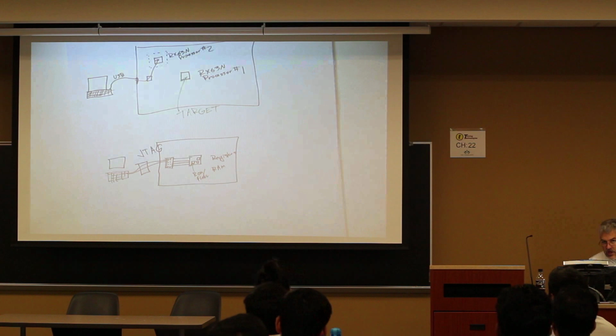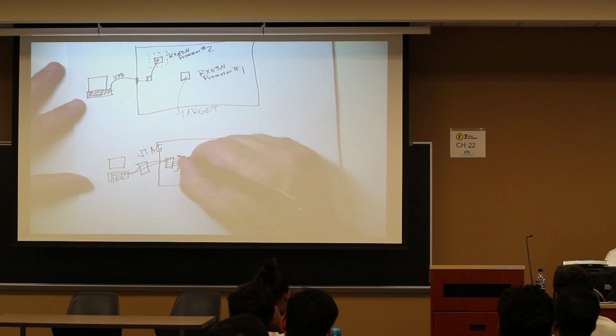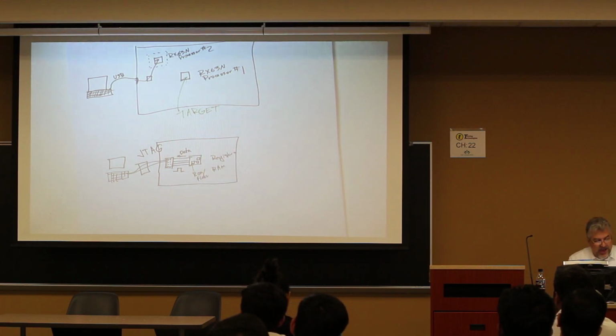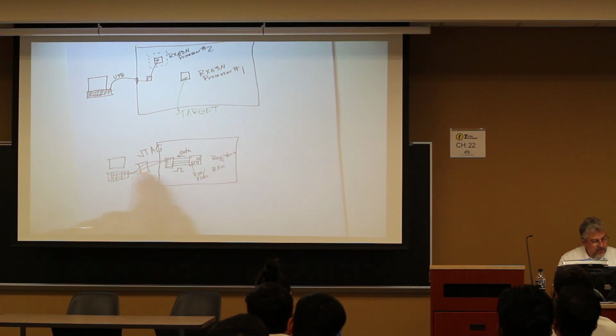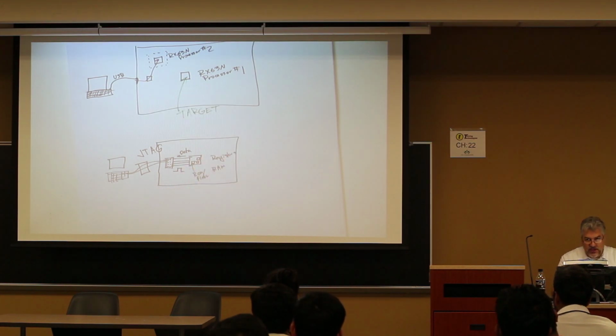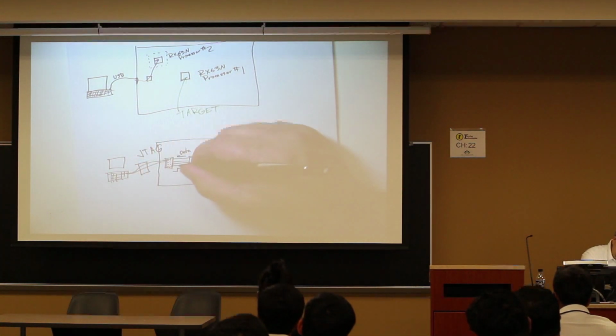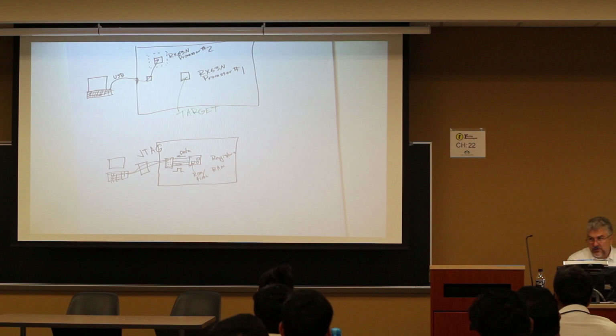And the goal of a JTAG is to provide a clock such that all the data can be clocked out. Data meaning the contents of the registers, RAM and ROM. And this clock will allow you to actually chain all of these devices such that the information can be clocked out, and actually you can clock other stuff in, like the program itself.